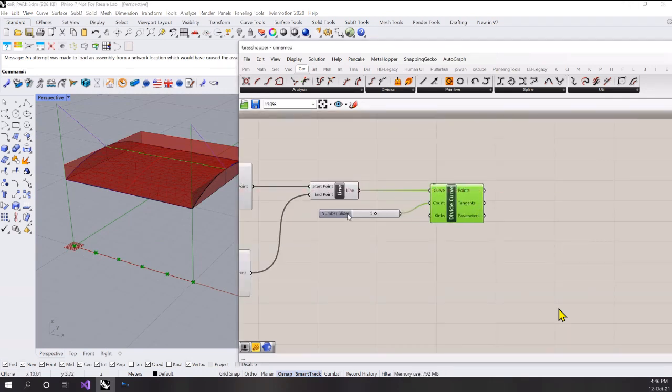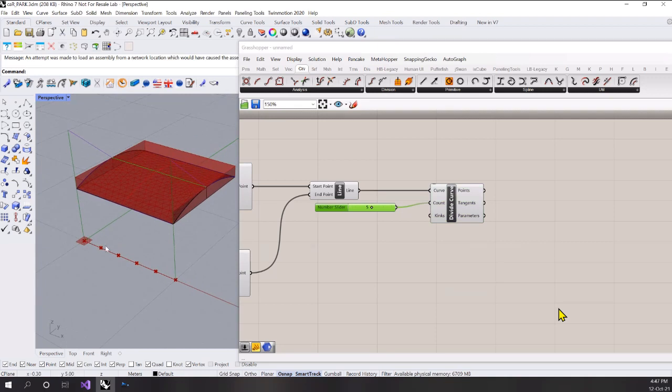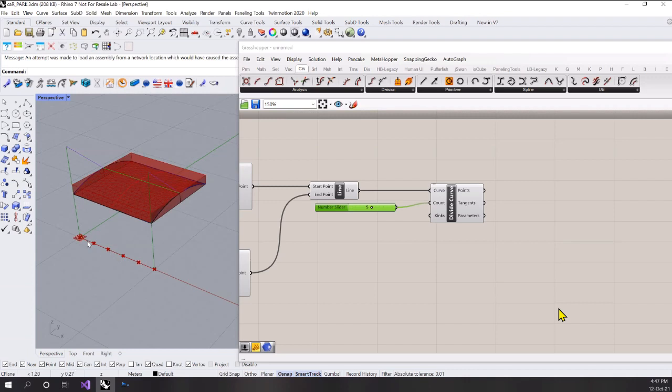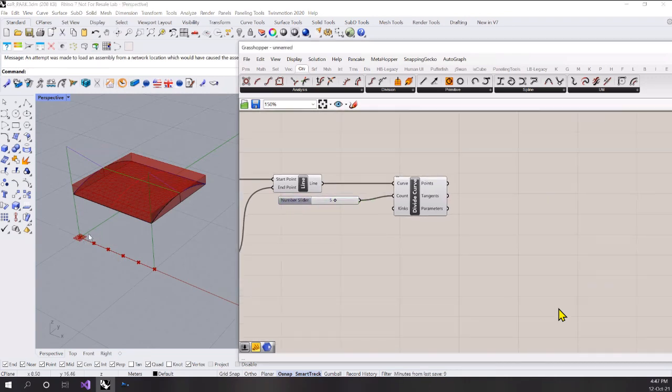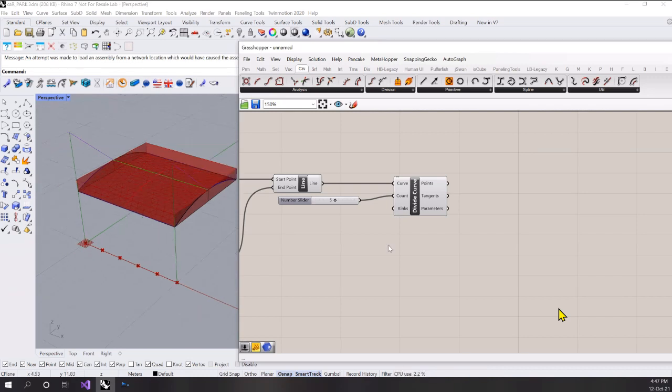Now that we have the points, I want to generate planes. Clearly, the planes here are YZ planes, and 1 plane for each of these points. So I can use this plane to slice my mesh. That's quite clear, I think.